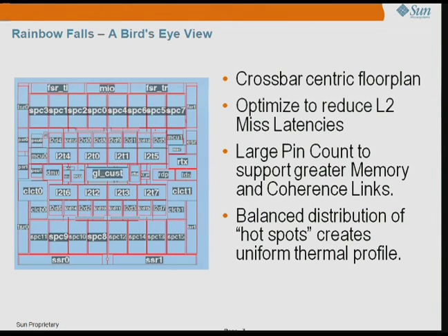Okay, so everything else is effectively arrayed around it, but in a symmetrical manner, because typically we have a power of 2 number in clusters. I/O is also very high in count because we support 6 coherency unit links, multiple memory channels. So there's a symmetric distribution of the links around the chip.